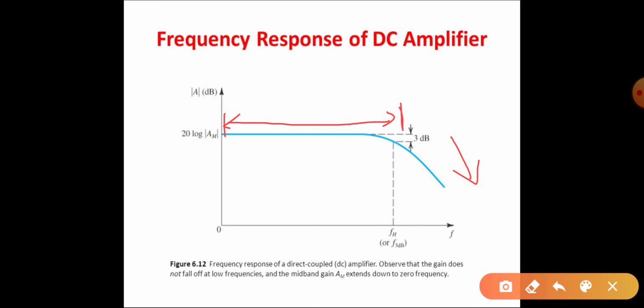When the DC bias or Q point is shifted in accordance with the signal frequency, the higher the frequency, the higher the variation in the Q point, and because DC biasing conditions are changed slightly, there will be a temperature variation in the transistors of this circuit. The variation in temperature will cause a shift or change in your Q point. As your Q point gets shifted, you will not get your desired amplified output.